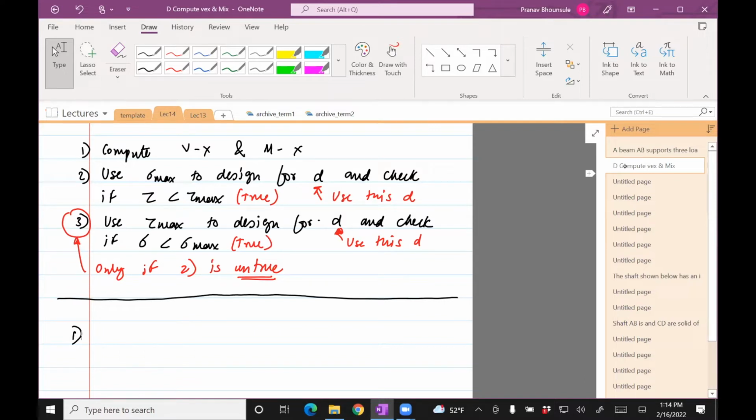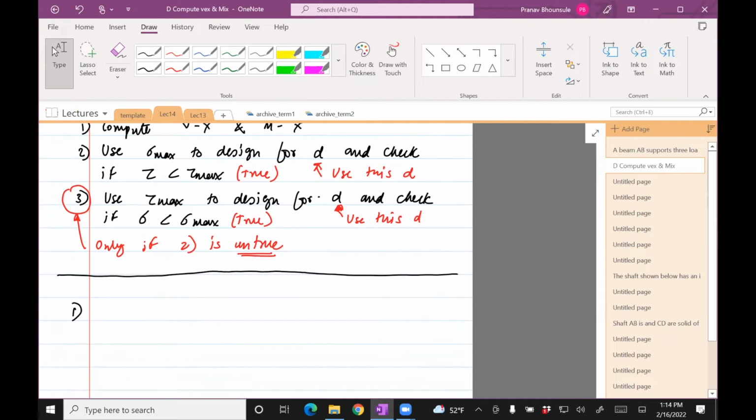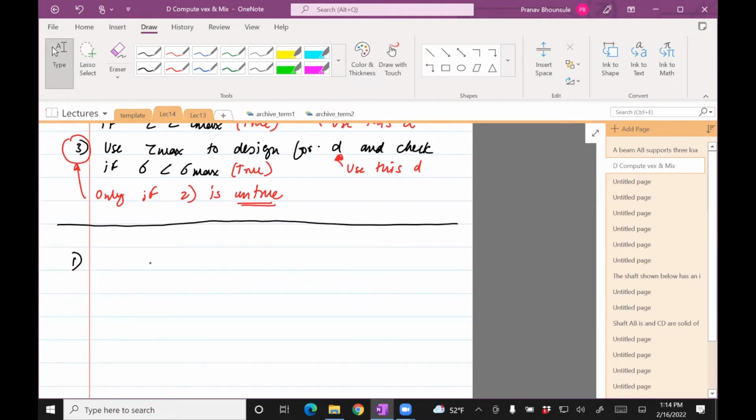If you assume pin and pin, then you will end up with two for the pin on this side, two on the other side, you'll end up with 4. And there'll be some ambiguity on the forces. In this case, the horizontal forces don't really matter. So you could assume that too, and it won't really change anything. So pin is fine, pin hinges, pin roller is also fine. So you can arbitrarily decide which of them you want to be a pin joint.